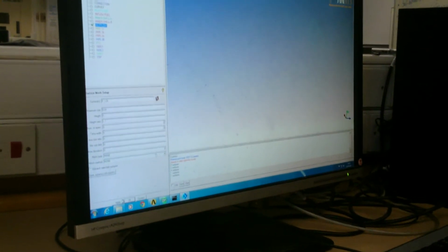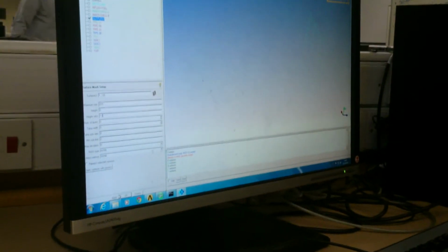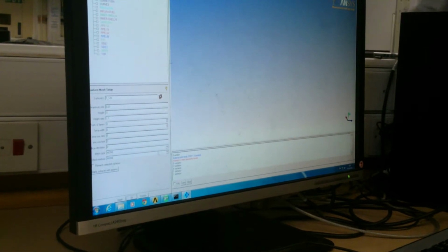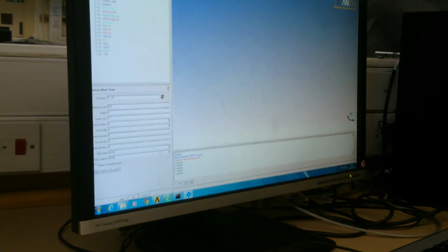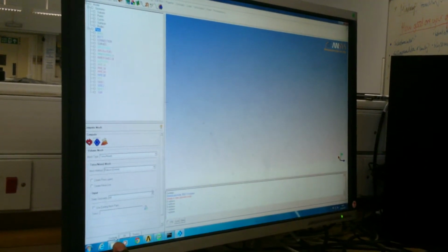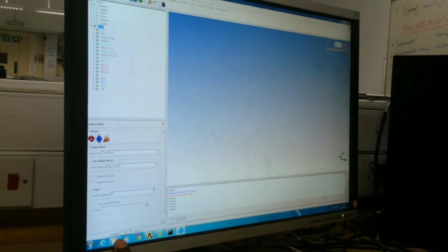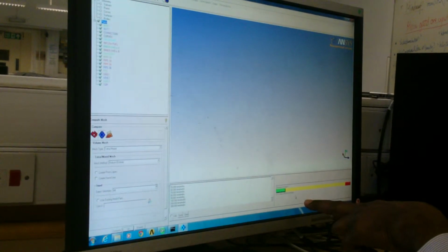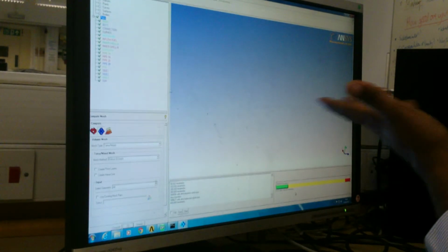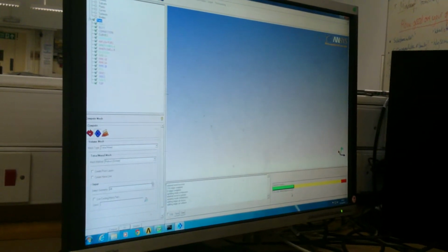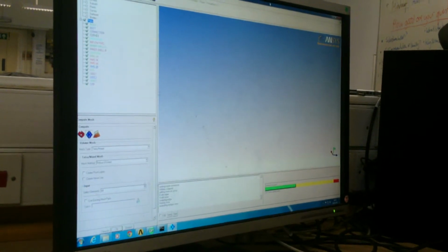Now I have built a sense about my mesh, right? I'm going to ask it to build a mesh, to compute the mesh. You press here, and then tell it compute straight away. Fingers crossed. And then let us see. If it goes to a million, stop it. If it gives you a decent mesh, okay, 3,000 mesh. That's not bad, in my opinion, although you can improve on it.